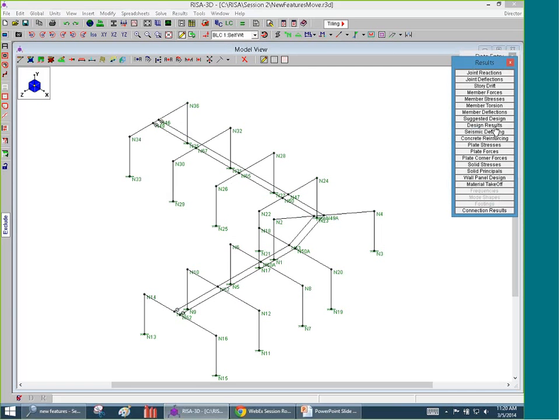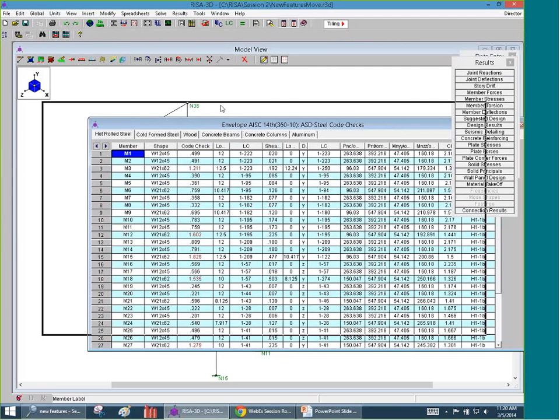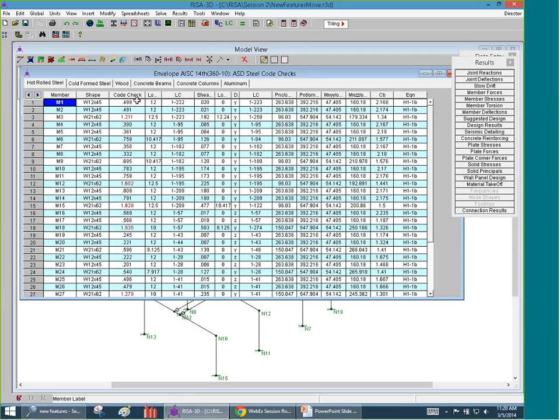And it's going to show me the design results here. If we look at the design results, we see that I do have some failures, and it's interesting to see what my failures are. So it looks like I have a failure here of 21% overstressed, and I have it at a load step. If we look at the load combination, I only ran 1 load combination, but that dash number is showing me dash 223. That's the load step that was causing that failure.